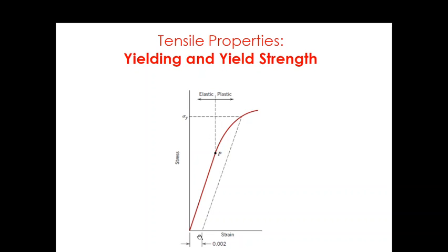Generally, find the point where strain is 0.2 percent, and from 0.2 percent strain draw a line parallel to the linear line. You can see this line, and it will cut the curve at this point somewhere here. The stress corresponding to this point we call sigma y 0.2. It means the yield strength corresponding to 0.2% strain, and this yield strength can be used for design calculations.